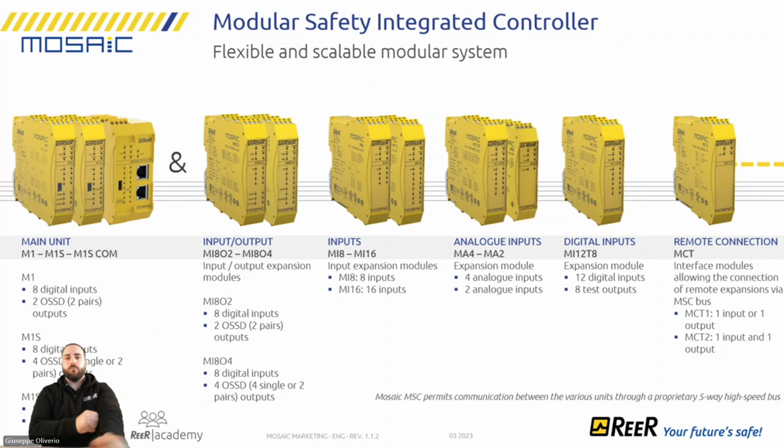And let me tell you this, when you have the 4 OSSD device, you can also change the configuration with 4 single or 2 double channel output. So everything is configurable. Then, if you need only inputs, we have the MI8, MI16. MI8 is 8 more inputs, MI16 has 16 more inputs.